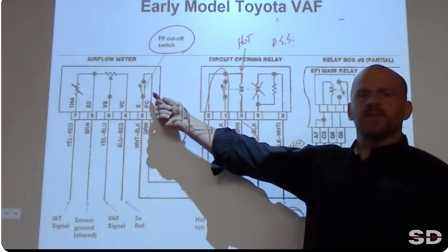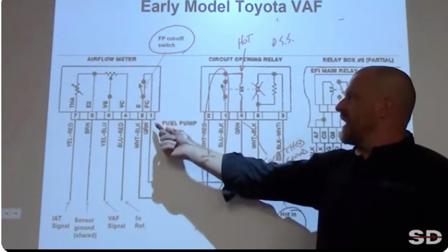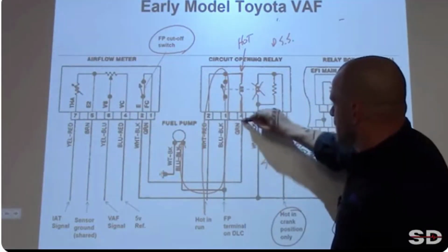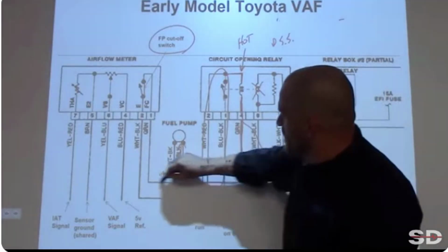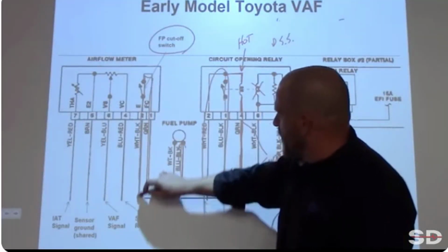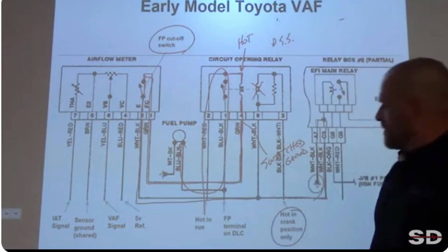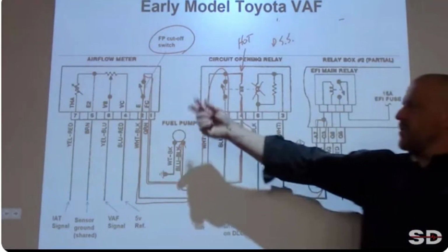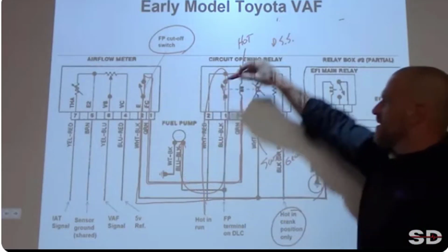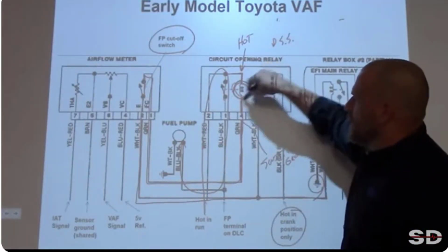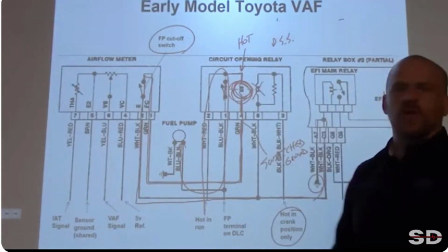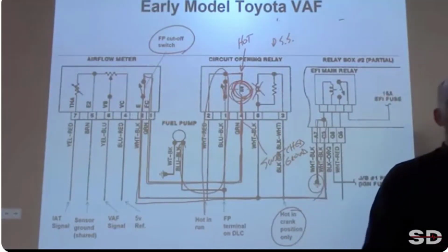This switch closed, which did what? Connected this leg of the circuit. I know it's the same color, but follow my ink to what? Ground. So is the car continuing to run? Yes, because this coil took over, made a magnetic field, and is holding that closed. The rest of the time the car is running.